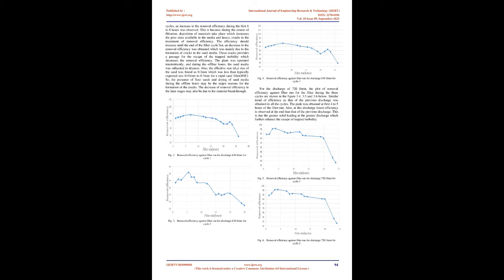than the conventional tanks. Rapid sand filter. The 2 units of the RSF are provided which receive water from the tube settlers separately. The RSFs are run simultaneously to get the purer water. A set of 4 valves are provided which can be easily used to get one filter running while the other